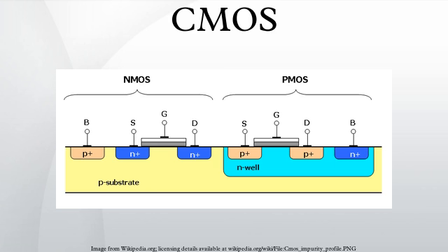Due to the De Morgan's laws-based logic, the PMOS transistors in parallel have corresponding NMOS transistors in series, while the PMOS transistors in series have corresponding NMOS transistors in parallel.